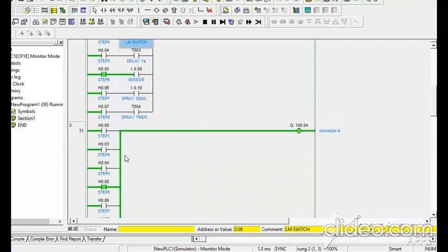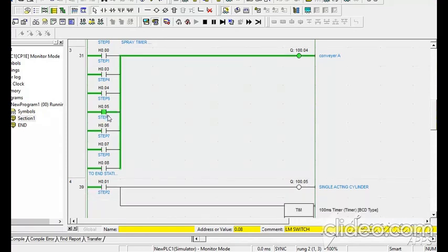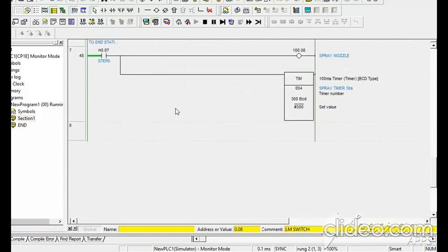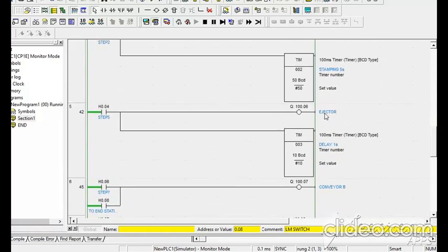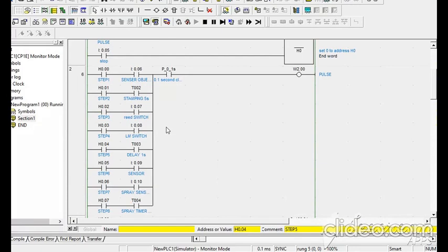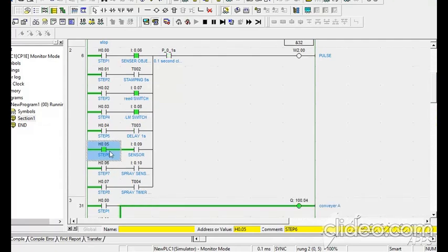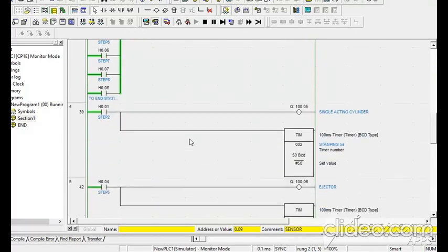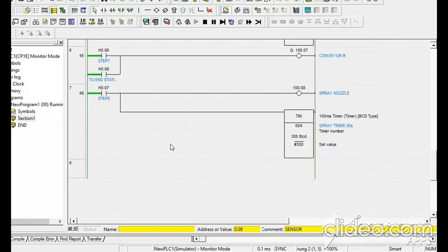Okay, this one will keep on going as required in the question by step number 6, H005. And also what will happen is we have the ejector. The ejector should work, which is H004. Let's go up now here, but the delay is 1 second. That's why it has moved already, and now it's in H05. So H05, which is step number 6, let's go to H number 6. Now the conveyor will still also be working, and H number 6, let's go.